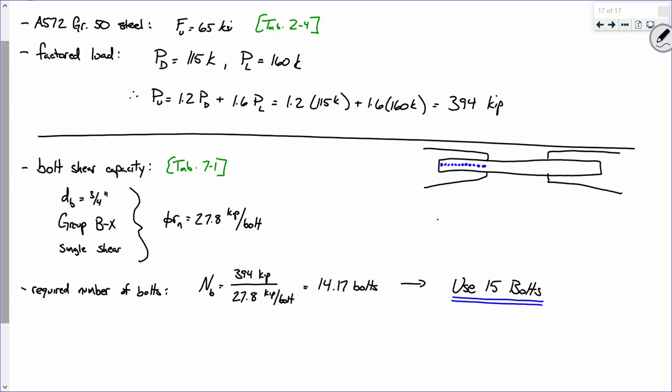Now, what I'm saying is this. Here's my design, assuming it's the same member size. We only have a gusset plate that's about like that, and we just collect those bolts in a smaller group. You get the idea of the scale? Now imagine this member is repeated 80 different places in the structure. That is a lot of additional steel that's just being wasted, okay? You got to think in larger terms, think of the whole structure. That's just going to make those connections ridiculous. You see what I mean?